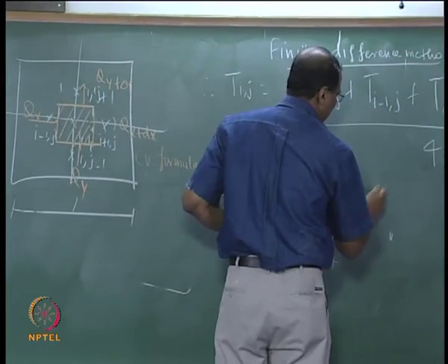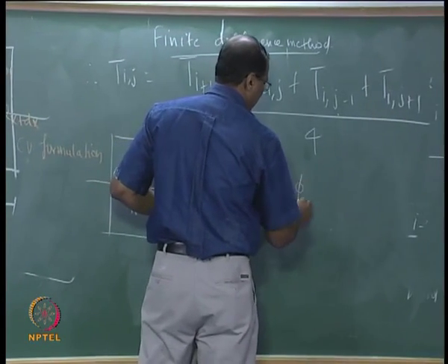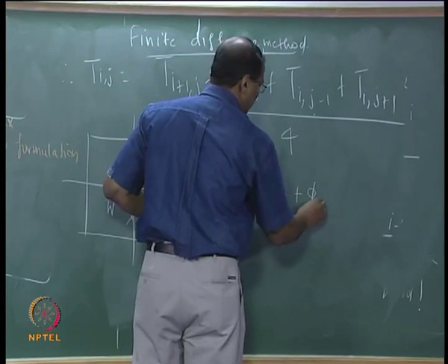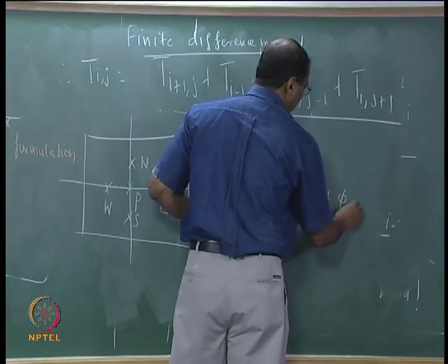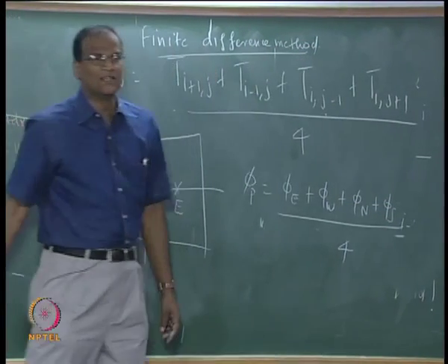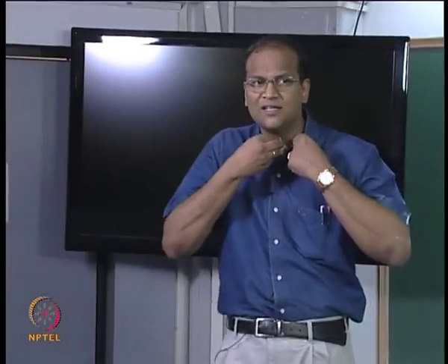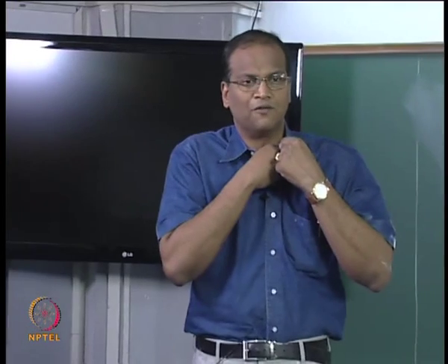So the basic story is the nodal value for a diffusion equation is east plus west plus north plus south divided by 4. The divided by 4 comes because you get 25% weightage to all of these. Otherwise, when you write your CFD software, it is always like this.